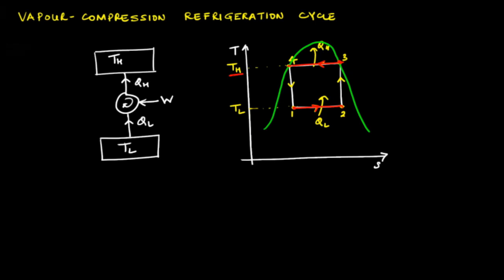equal to the saturation pressure corresponding to the high temperature TH. Among all these processes, isentropic expansion of the saturated liquid at state 4 to wet vapor at state 1 is difficult to realize in practice. Moreover, the substance during process 4 to 1 will be mostly liquid. Therefore, if a turbine is used to isentropically expand the substance from state 4 to state 1, there will be little work output from the turbine.